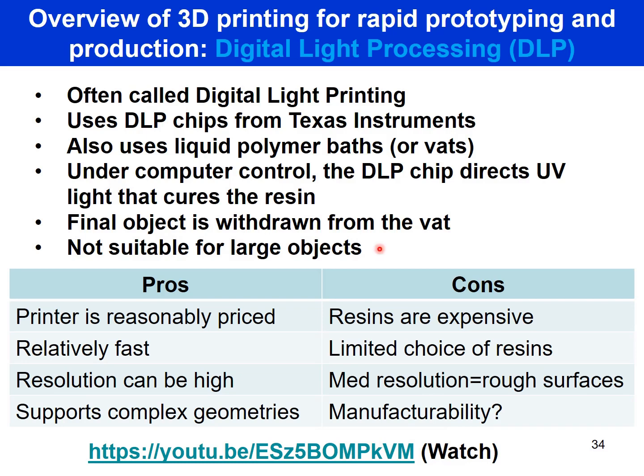The advantages are reasonably priced, relatively fast, resolution can be high, and it supports complex geometries. The disadvantages are limited choice of resins, medium resolution, that is to say rough surfaces, and manufacturability is still under question. There's a nice video I recommend watching because it's really interesting.